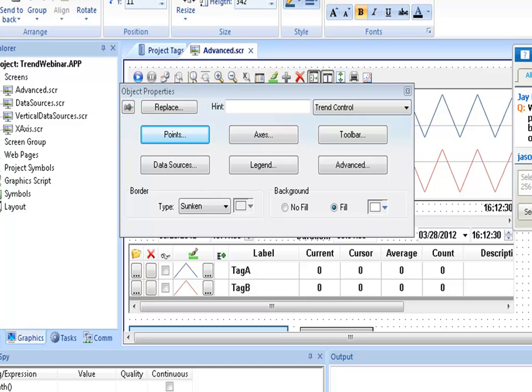So this is pretty much the fastest that we were able to save data. And actually another bottleneck is how fast we can acquire data from the actual PLC. In cases where you need something faster, like, I need one value every 10 milliseconds or 1 millisecond, whatever it is, like for instance for vibration analysis, you need to collect data and save data really fast.